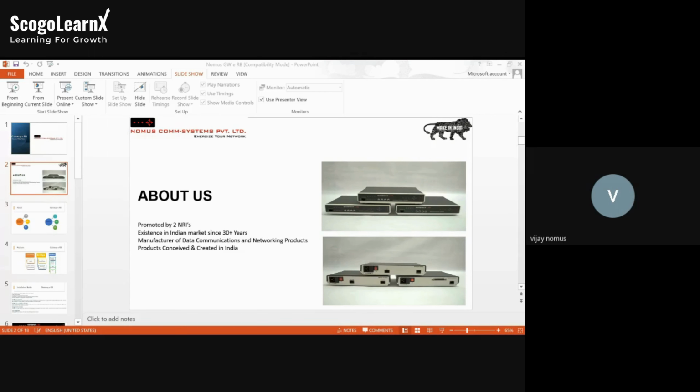And one WAN port, which is a 25-pin D-type female connector for the V35 interface. For example, this is for the RB V35. For the RB E1, we will have one adapter box, where one end is RJ45 and the other end is a terminal block for connecting the TX and RX cables from the MUX.